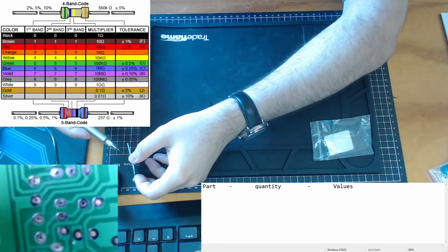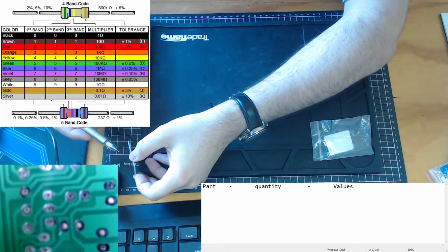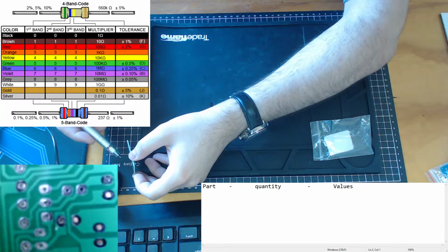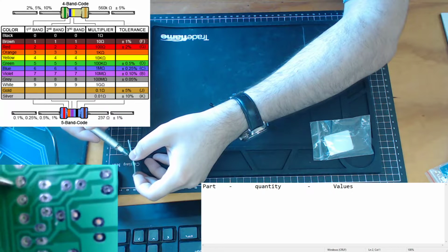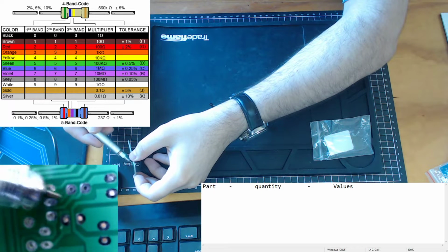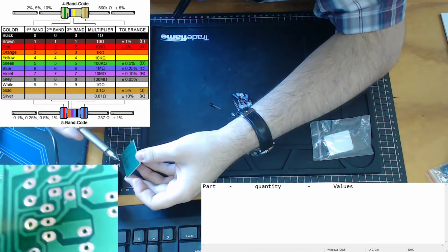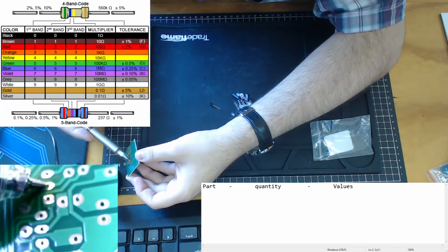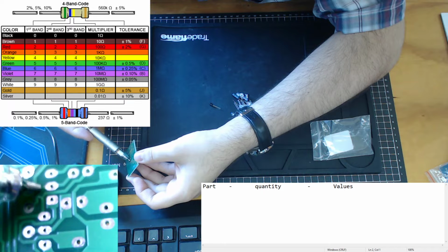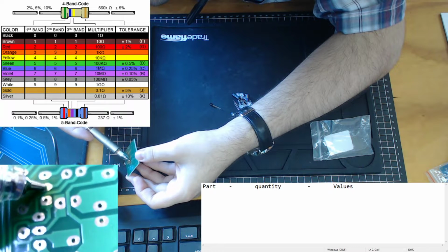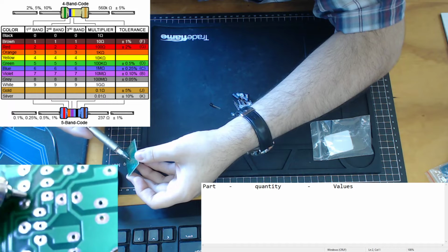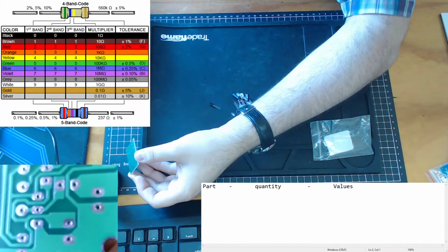Now if we put enough heat on this with a soldering iron or a heat gun or fire, or if the circuit itself overheats due to creating a short circuit, that lacquer itself can melt and it can cause other short circuits in our system. If we look at an example between this square and this square, we see there is a line connecting them. With that light green line, that means that if we were to remove the lacquer, that would be a solid copper trace between those two dots. So they're equivalent to soldering a wire connecting those two areas together.